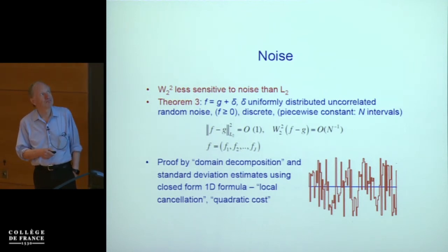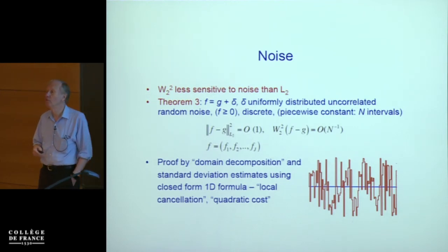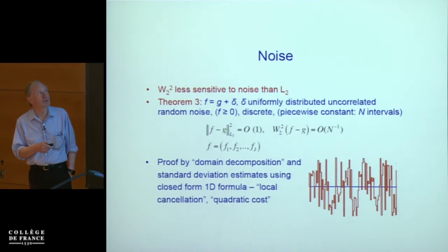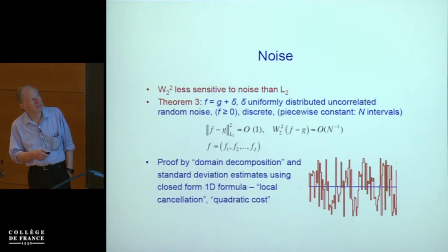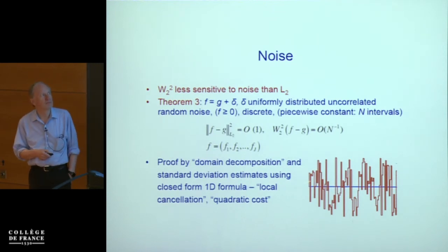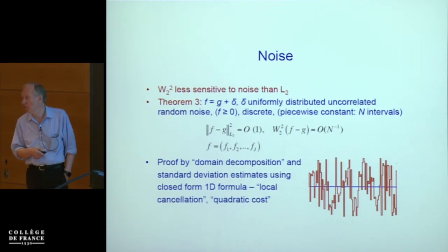So you have typically your signal here, not your computed one. Well, there is also sort of numerical noise there, if you could call it that. But the true noise, of course, is measurements over there. And it's not seen so by the Wasserstein distance. So if you take a signal over here and you add bounded, uniformly distributed noise, then you would see that the Wasserstein distance between these, even if you have a 0.01 noise over here, is very small, while of course if the variation is over 1, or the standard deviation, then you would get a 0.1 result over here.